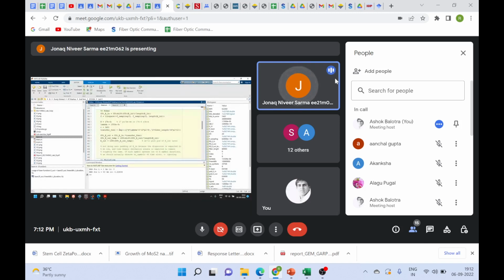We know the frequency domain transfer function, and this transfer function is then multiplied to the input signal. So we know the convolution in time domain is just multiplication in frequency domain. So doing this calculation in frequency domain is very easy. That's why we do it.